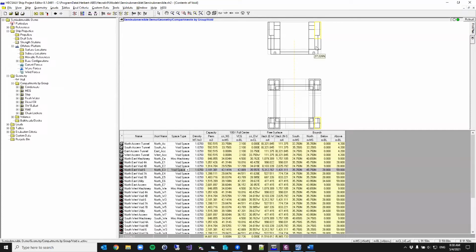So anything above 12 meters within this range is going to be the same damage set until I get to basically 5 meters below this flat, at which point I'm going to start hitting both cases here. So my critical drafts, you have to think a little bit critically about where these draft cutoffs are and where the damage cases and the extents are going to transition from having one set of damage cases versus another set of damage cases.